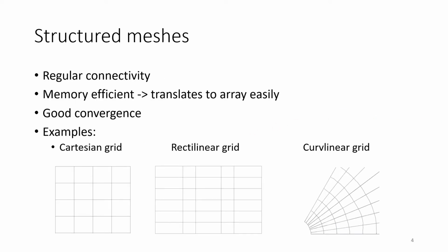When I have rectangular or quadrilateral meshes, I'm often talking about structured meshes. Structured just simply means there's a regular rule behind how this mesh was generated. And that means when I know where I am, I directly know who my neighbors are, right? So we go for such a Cartesian grid, which means each cell has a similar size.